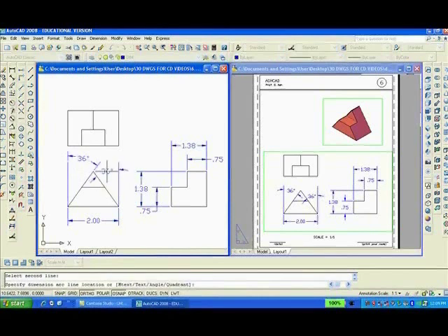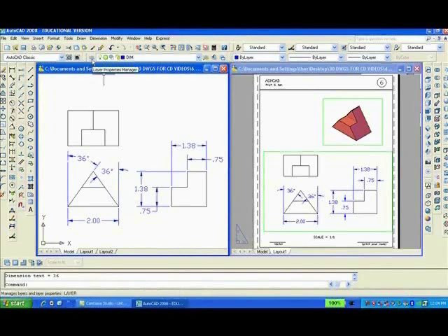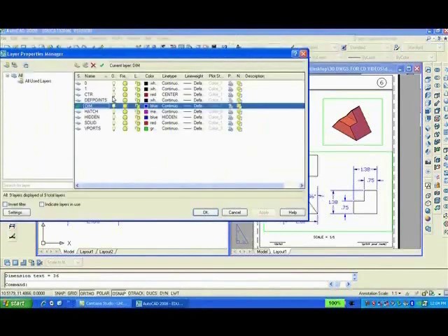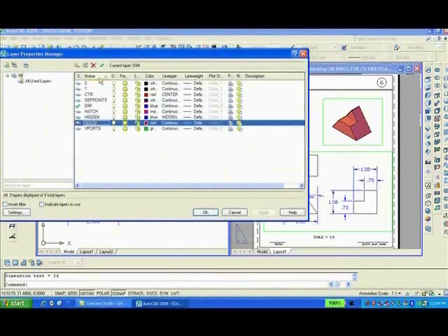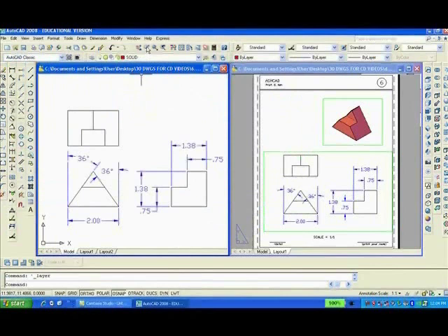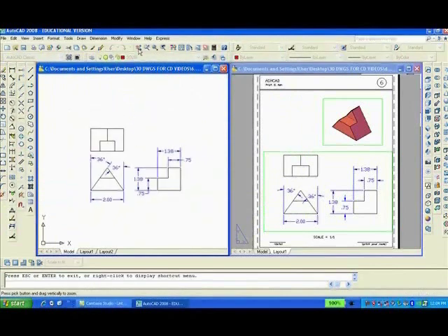Like that. So the drawing seems to be complete as far as the three views and the dimensions are concerned. Next, you'll want to draw the solid model. So you click on Layers, make Solid Current, use Zoom Real Time to shrink it down, pan over a little bit.